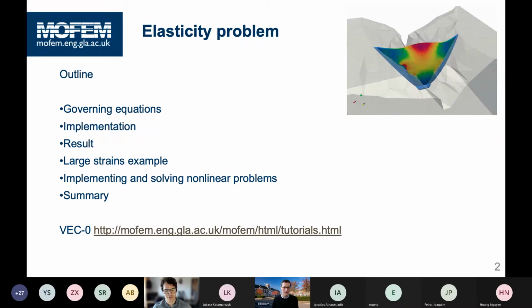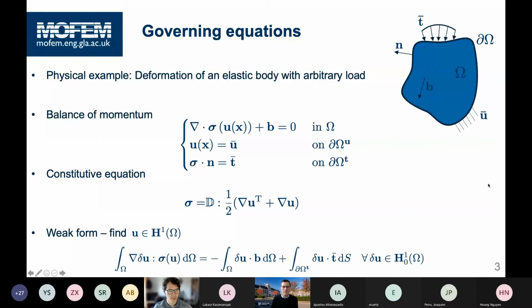So the goal of this presentation is to show how to solve vector field problems in MoFEM in 2D and 3D cases, implement and solve a nonlinear problem, and also simple methods to verify the convergence and tangent stiffness matrix. So let's consider an isotropic linear elastic body under prescribed body forces, boundary conditions, and displacements. So our problem is to find displacements that satisfy the balance of linear momentum and those boundary conditions.